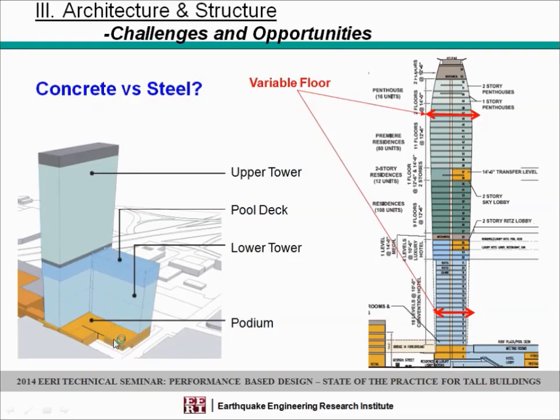So we had backstay issues, we had major transfer. It invokes a lot of comments that were made earlier about proper modeling of your diaphragm for transfer of forces and relative stiffness of your diaphragm versus your vertical system.